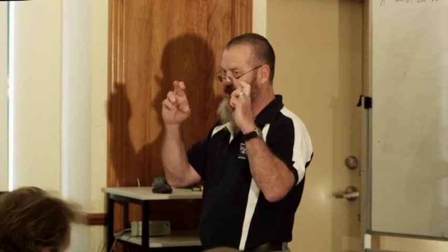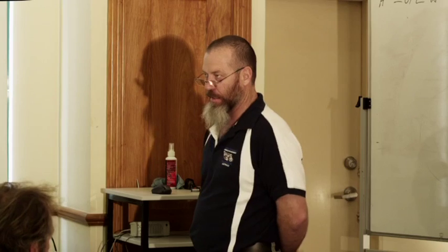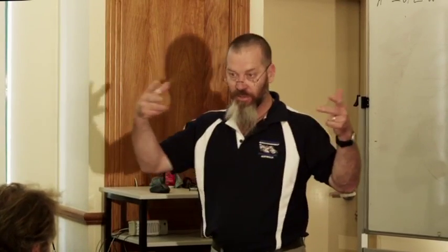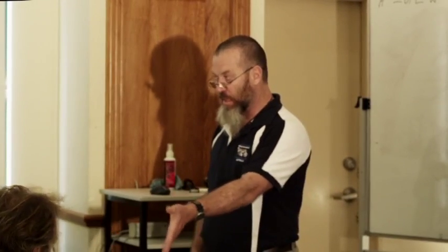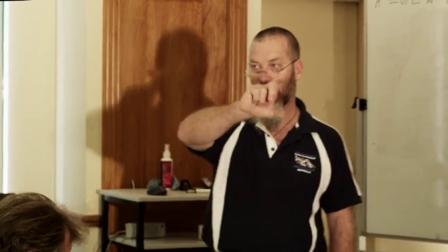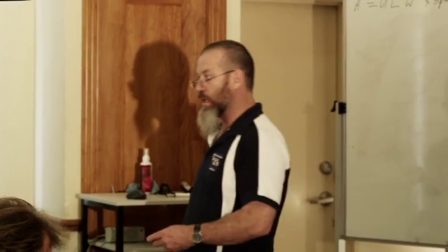Now, how many of you, apart from the fella in Cairns, I hope he does this all the time, please tell me you do. Yeah, sure. Thank you. Whatever you want to hear, he says. How many of you have actually done ridge connections like that? And the answer is not a lot of us, even myself, honestly. Some of the stuff I did back in Mackay, I never used to do that. I was always told that 2 skew nails either side of the rafter was good enough. Well, it ain't. The minimum connection you should be doing is that board there, that piece of 75 by 38, down underneath the ridge. And you can see how that works.